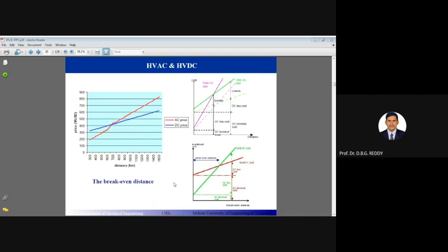Okay, these are the basic differences between AC and DC transmission. In coming days, more DC transmission lines will be used. Why? Because cost effectiveness is good, stability is also good, and you can operate from one region to the other region. If the 2 systems have dissimilar frequencies, you can connect asynchronous mode to synchronous mode easily. These are some advantages of HVDC transmission. Anyway, this paper will come to you at level 3.1 or 3.2. Okay, no problem. Just a little bit of introduction.